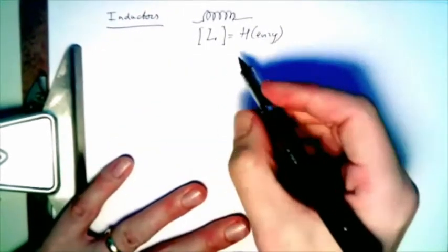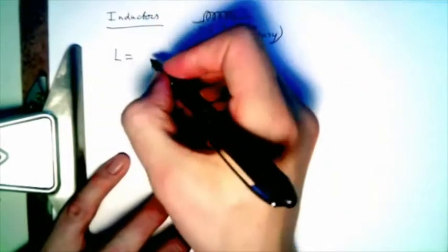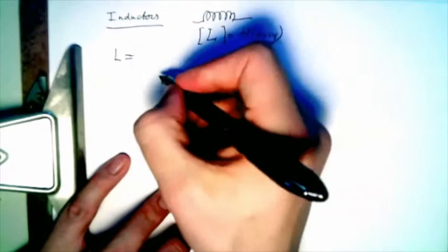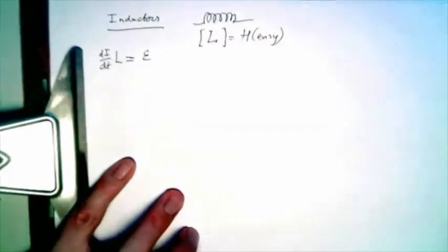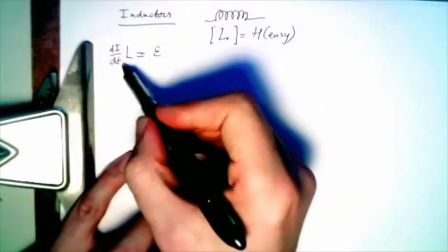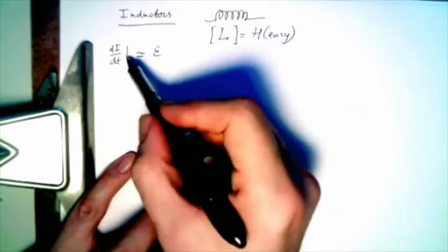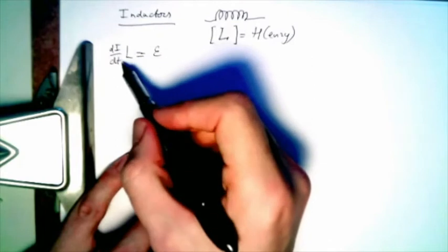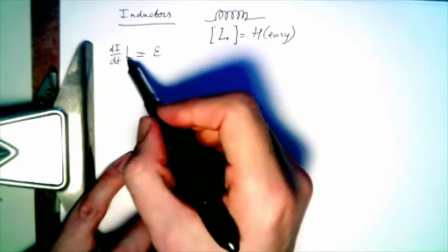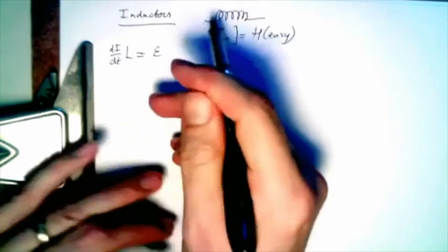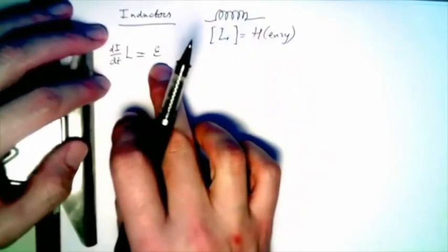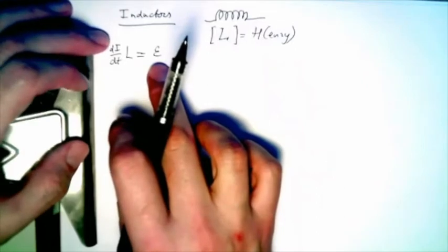And we have the basic rule that L di/dt is E. So the EMF that gets generated is related to the rate of change. And remember, underneath the hood, this current generates a magnetic field. The time varying flux that this inductor sees is therefore generating an EMF, and that's neatly, compactly written like this. So it's really two Maxwell's equations written in one.